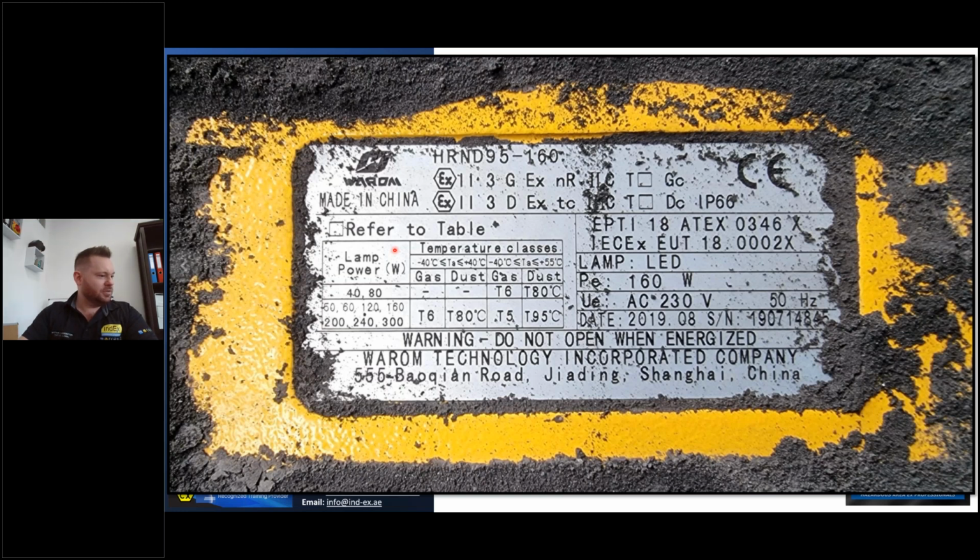If you inspect a grain silo, 50 to 70 years old, and the equipment was not rated but is connected with conduit, and you felt based on a risk assessment that you did that the IP rating was maintained, would you submit a failed inspection sheet? An old installation has to be inspected to those standards that were applicable at that time. Myself, I would do a risk assessment to ISO/IEC 80079-36 and compare the 13 sources of ignition. I would consider industry past experiences, explosions that have happened, and look at the failures of items.